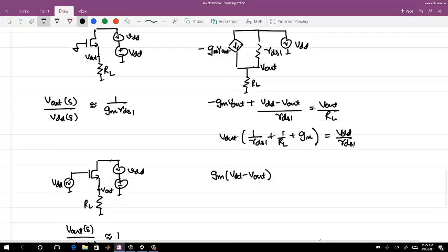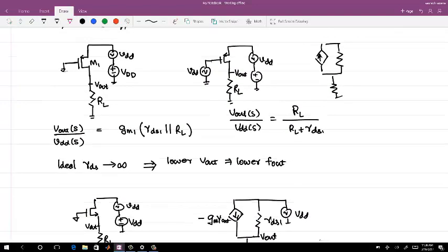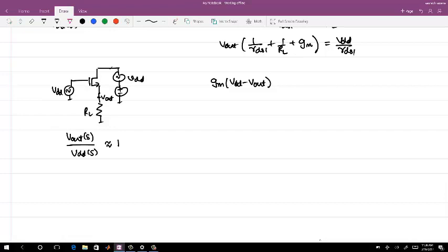So now you see that depending on how the gate of this output stage is controlled, you will have supply noise regulation to the output control voltage of the oscillator. Whether you will have the gate tightly coupled or not actually depends on the amplifier stage. So let's see that too.